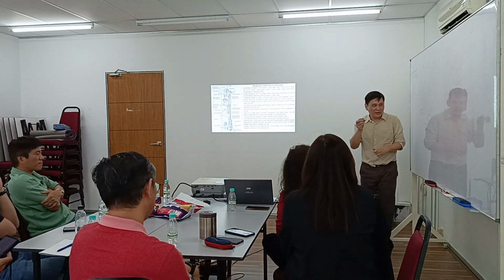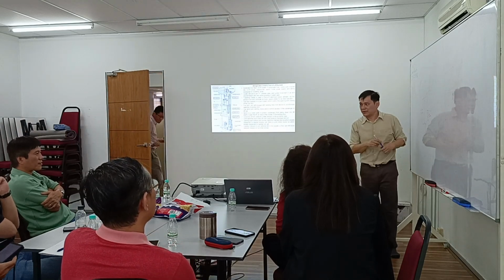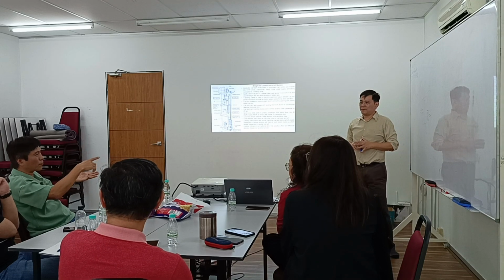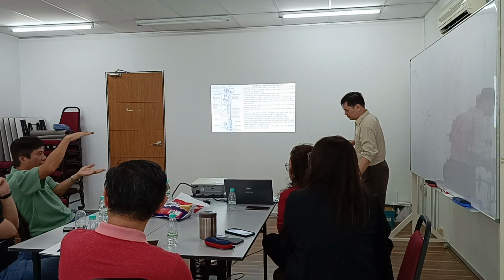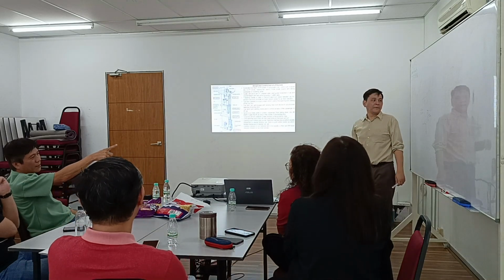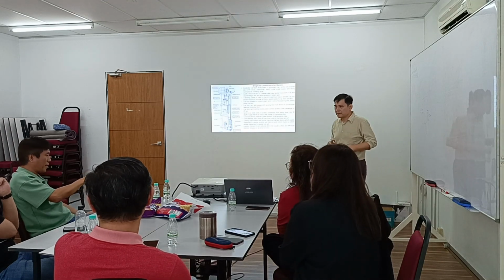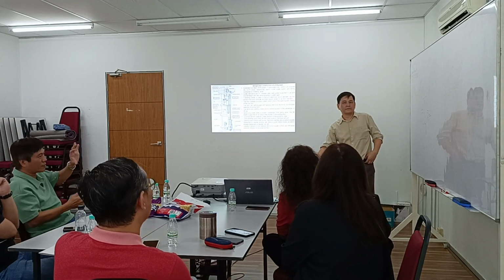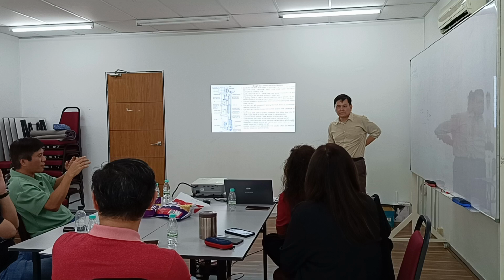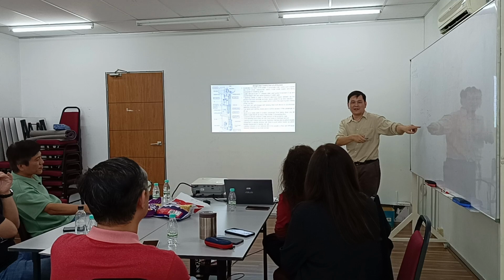I think in the past, actually very small only, then at one time JKKP said no because it was considered people could fall down. Now also you have the interlocking device: the car and the landing door must be almost level, only then you can engage the open. So hardly can you fall in, because you need to be sort of level. A little bit different, of course, you still can open until a certain level, the car and landing door and car door. Behind the scene, they are engineering the logic.